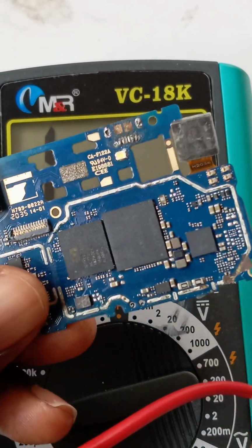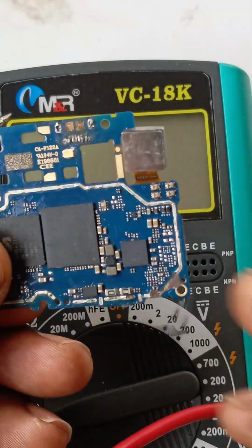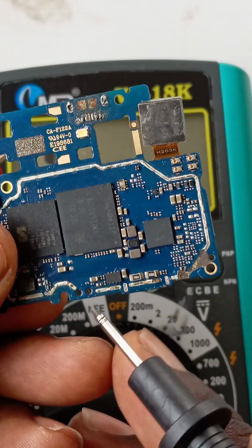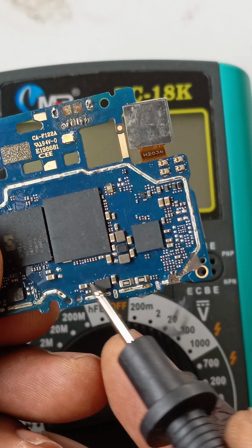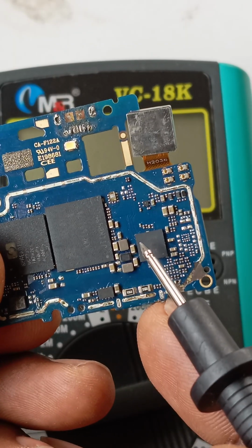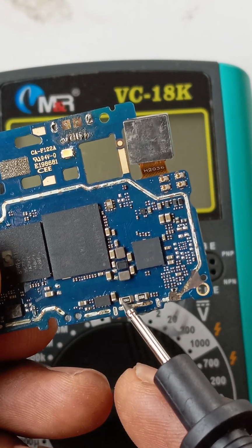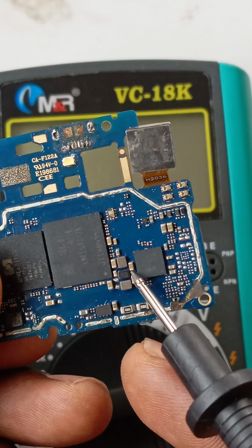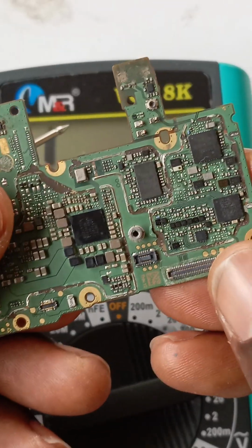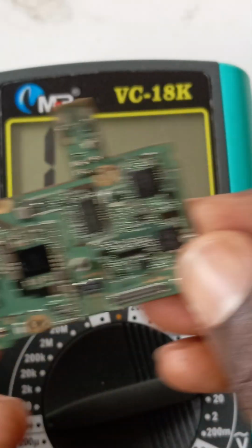So in order to know if the voltage is coming into the power IC, what you can also do is connect the battery to the phone, and even without powering on the phone, the voltage is going to pass through the power charging IC and come to this resistor in order to supply this power IC. So you can check the voltage by connecting the battery and then check it here. If you don't see it here, then this one is having a problem. The same thing also goes with this one.